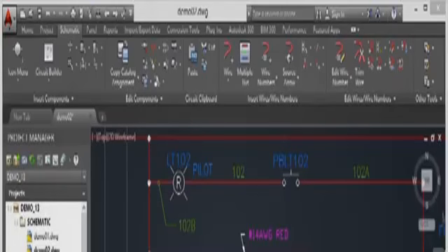So again, I select the component, right click, attributes like so. It does go slightly off the screen again. Don't worry about that because we only need hide attribute. And then I select on and it goes away and I press Enter. The issue is, once I've hidden it, how do I get it back?